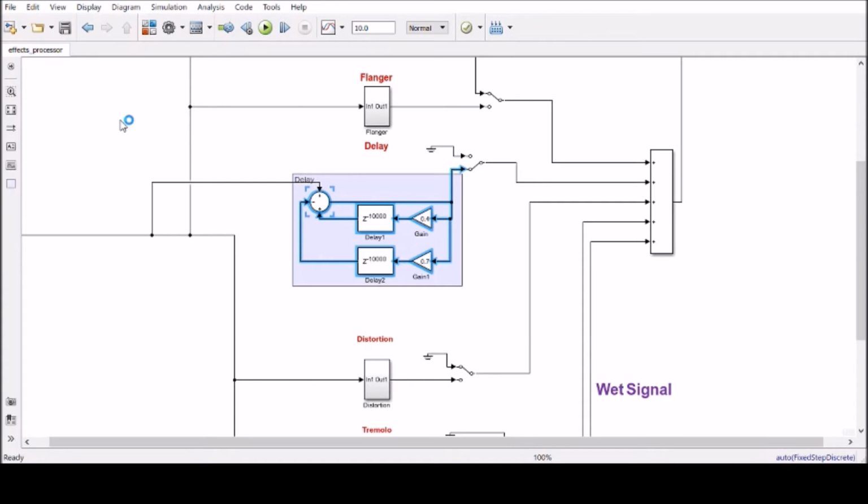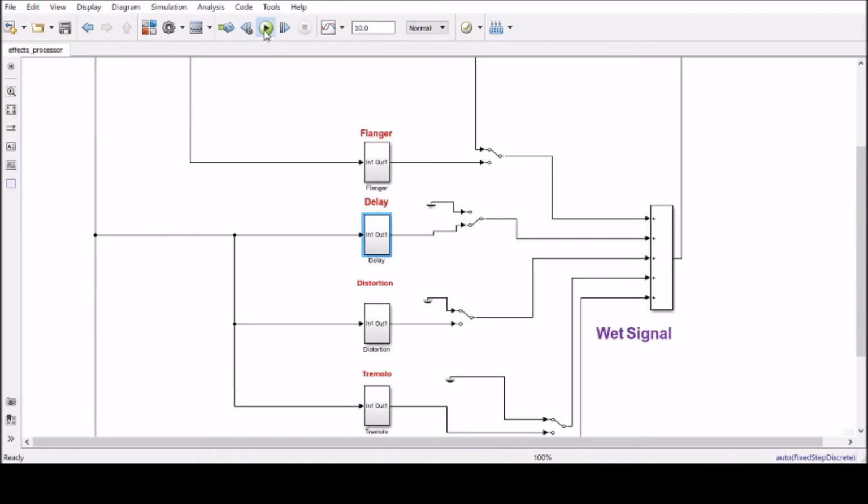The original audio is sampled at 44.1 kilohertz. So this adds a delay of 10,000 samples and applies a gain of 0.4 to it and adds it to the summing block. And here we see an identical delay with a higher gain applied to it, and it's actually subtracted, which gives it more of a decaying effect. It's more effective than the functions version we saw in the last video. So I'll play that back. You can kind of hear that decaying echo in the background there.